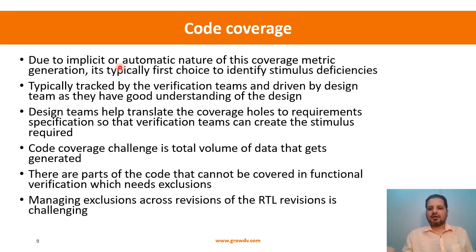And the way to achieve 100% is whatever cannot be covered within the purview of the functional verification, and whatever you cannot cover because it is not required, or that the design team thinks is a low risk item which doesn't need to be covered, they are all waived off. So a lot of exclusions get created for the code coverage, which are then applied to the report, which enhances the total results accomplished by the code coverage. And that is what you rely on to do the sign off.